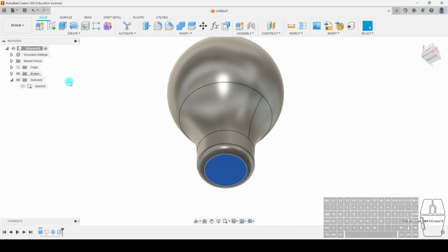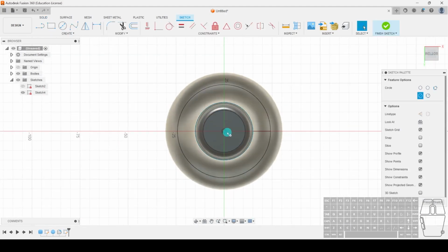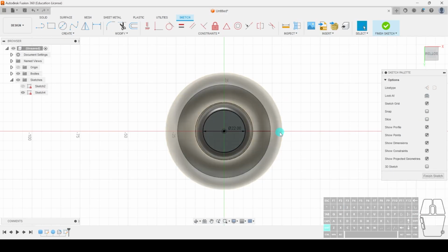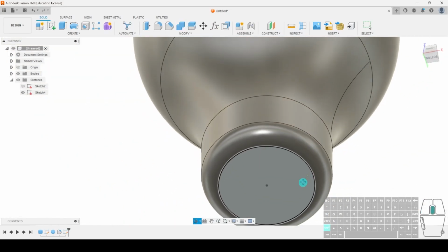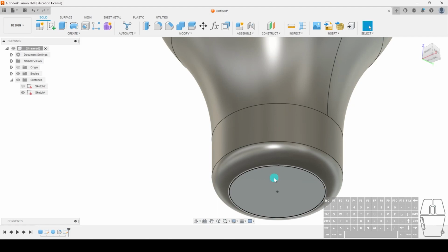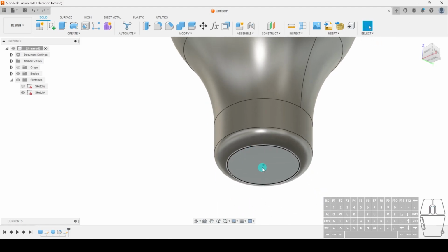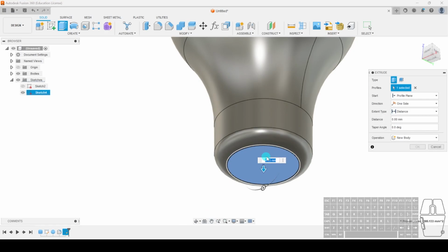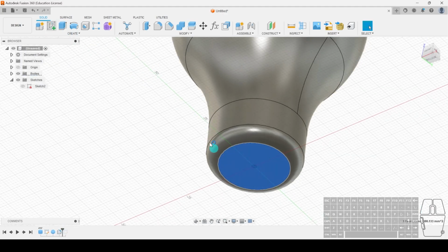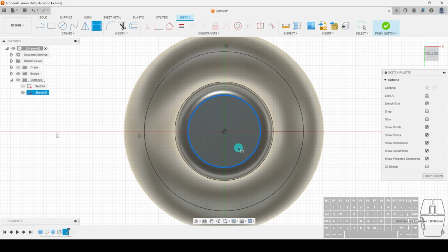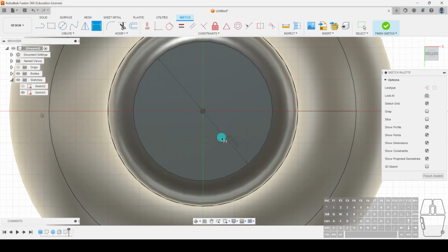Yep, can do that. So we'll do new sketch, circle, and we said we needed it to be 22. So you can see here our circle. It's more or less in line. Actually, wait, no, that's correct. So we have our circle in here, 22, just to make sure, because sometimes our face may not, if we go back here, our face may or may not. I think in this case, it should be create driven. Yeah, so in this case, it was 22, so that's good.